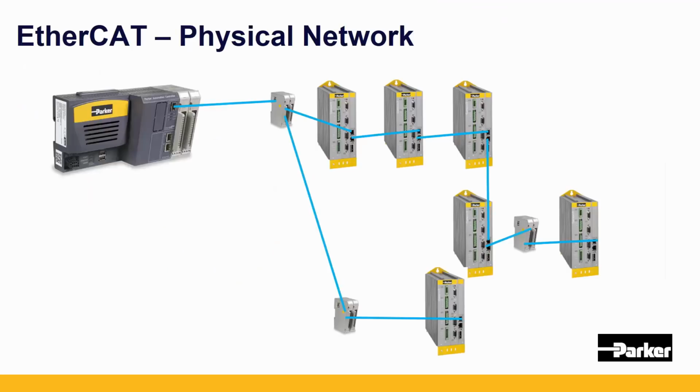So how is this possible? Well, let's take this particular physical network as an example. We've gone out the out ports and in the in ports. So let's see what EtherCAT does. How does our train flow through this network? The very first thing that happens is that the EtherCAT master, which in this case is the PAC, boots up and goes, hey, I am the master of my universe. I'm going to send out a packet out of my port 0 and see if there's anything out there. The very first port it goes out of, trick question, is actually the PAC IO port on the side of the PAC, and it addresses each one of those items as 1 and 2.